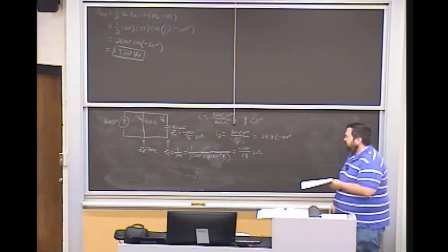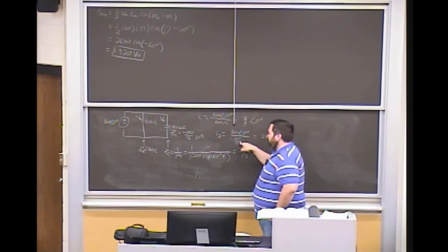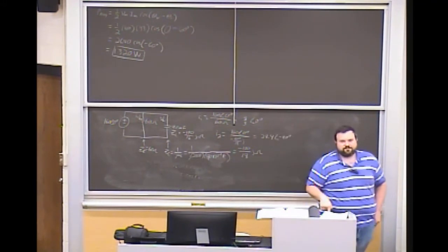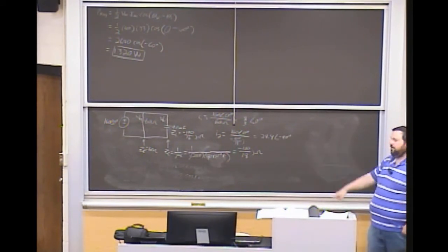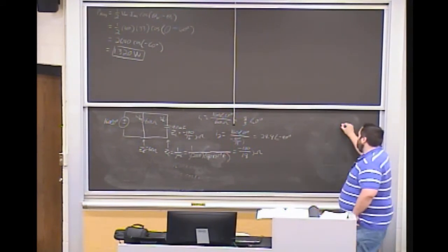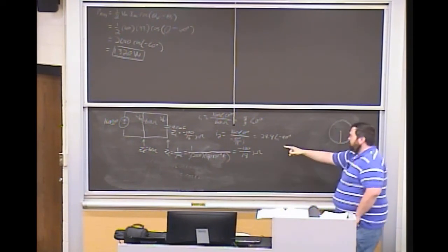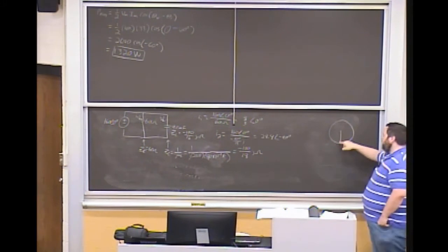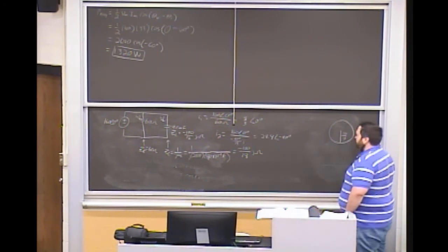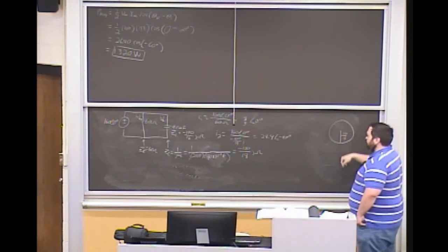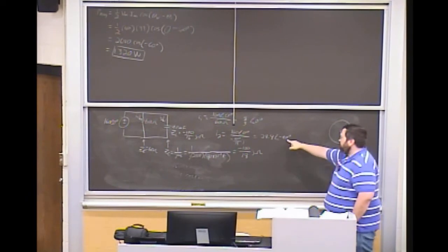How did I get that? Well, if I look at just the magnitude of this, convert this into a phasor, where is my negative 100 over 18 going to be? Think about my unit circle again. It's all multiplied in the negative J, so I've just got a magnitude of 100 over 18, and it's all going down, so my angle is negative 90 degrees.